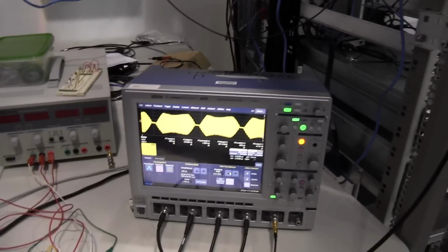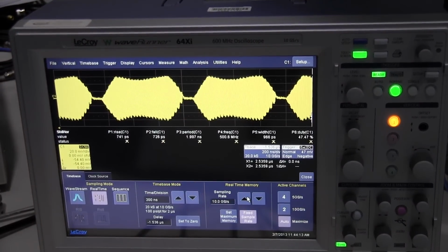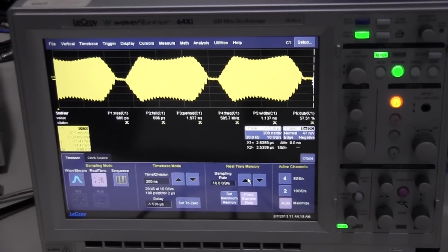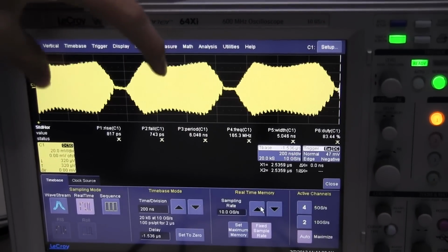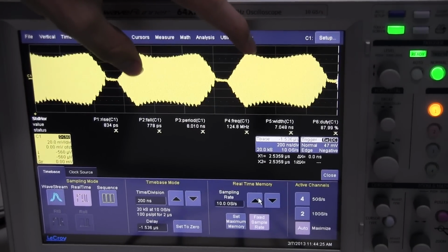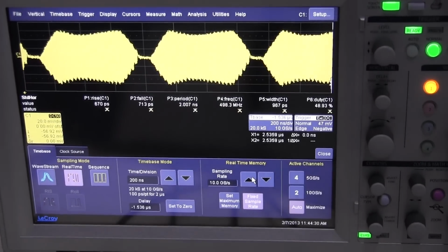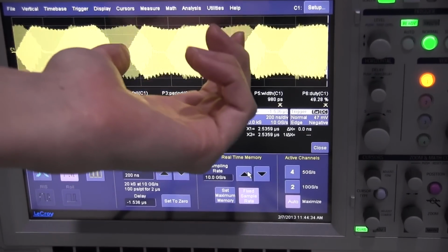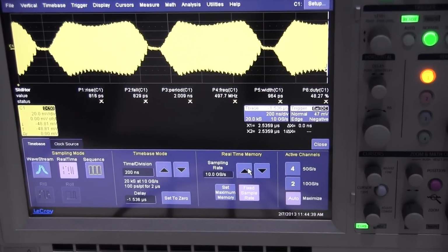So what we can actually see here is the signal from one of the beam position monitors itself. Each one of these is an indication of the amount of electrons in each of the bunches, and each of these is one revolution. It's done a full cycle of the storage ring. Of the storage ring, yeah. So the frequency at which each of these large bunches will occur is 1.388 megahertz.